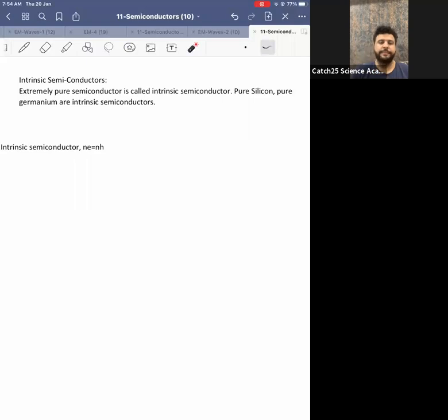So listen, look at me. I take one intrinsic semiconductor, I add something to it, so it becomes extrinsic. Because pure is intrinsic, if I add something to it, that is called extrinsic. The thing that I add is called dopant. The process is called doping, and then the semiconductor becomes doped semiconductor or extrinsic semiconductor.